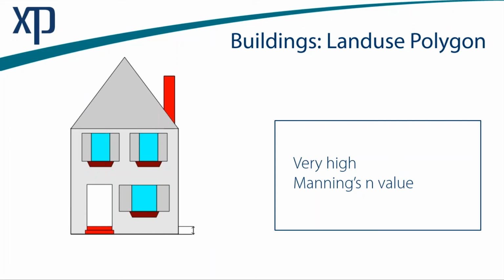But for certain types of modeling, this is totally acceptable. What if we had a very shallow flood and it was very fast moving, right? And it's probably not going to go into any of the buildings anyway, just a couple of inches. Manning's roughness would be fine. In other situations, we might want to use different treatments.